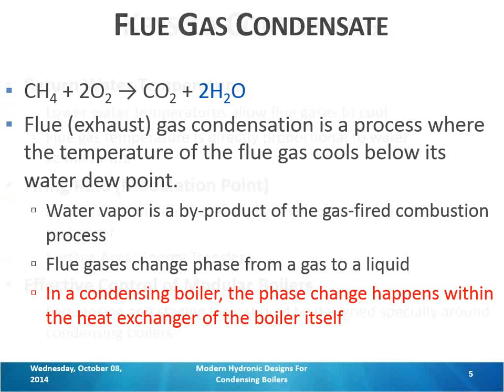But in terms of the controls, we're usually looking at our supply, and we're often ignoring the return that's coming back. Maybe it's looked at in the design day, but as soon as we get outside of that condition and into part load conditions, things change very quickly as the load changes in the building. So we're going to look at some of that today.